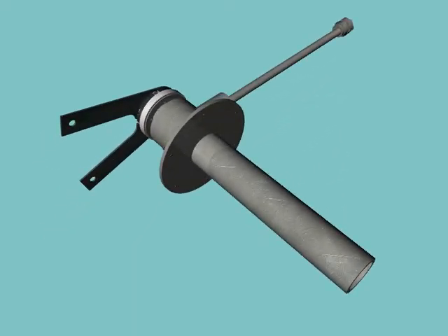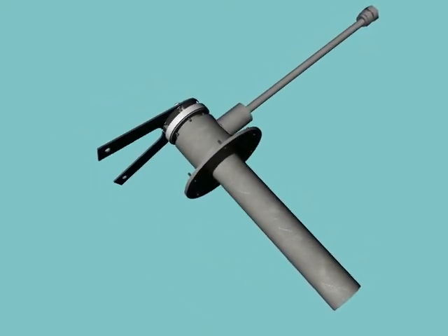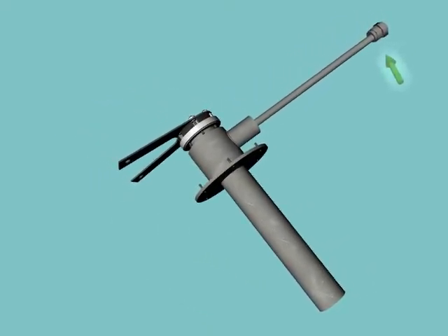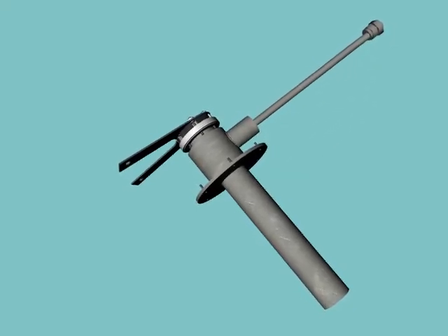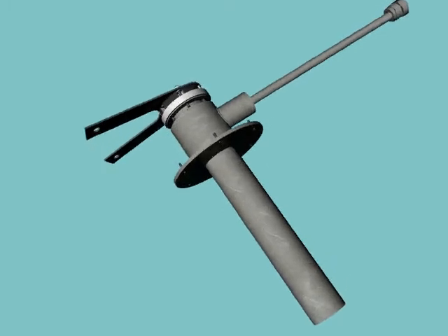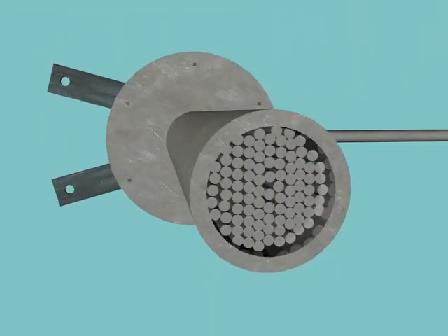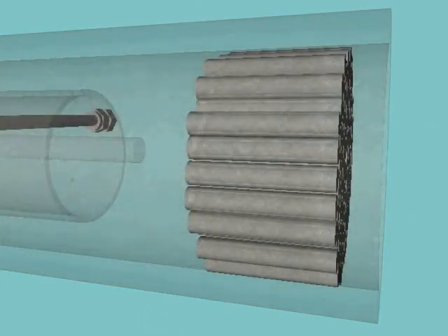The main body of the cathode is made out of pure tungsten. The lithium feed tube is made out of TZM molybdenum. This is a multi-channel hollow cathode, which means that at its tip it has 62 minor rods that create many channels. The current attaches to these rods, through which the lithium vapor flows.